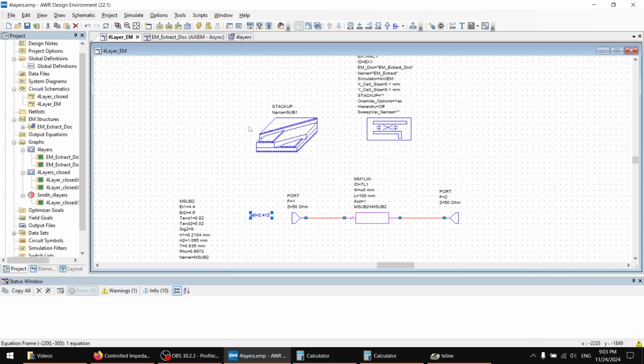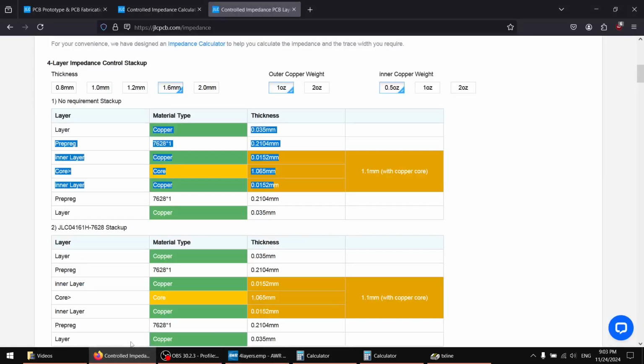So yeah, I think most of the structures with high impedance, like the low pass filters, will work just fine, and the other structures should also be possible. And that's all on a very cheap PCB, where you can also implement more complex digital circuits that might require you to change between the first inner layer and the second inner layer and so on. So part of the PCB can be digital, part can be RF, and this is something that I want to implement in one of my projects.